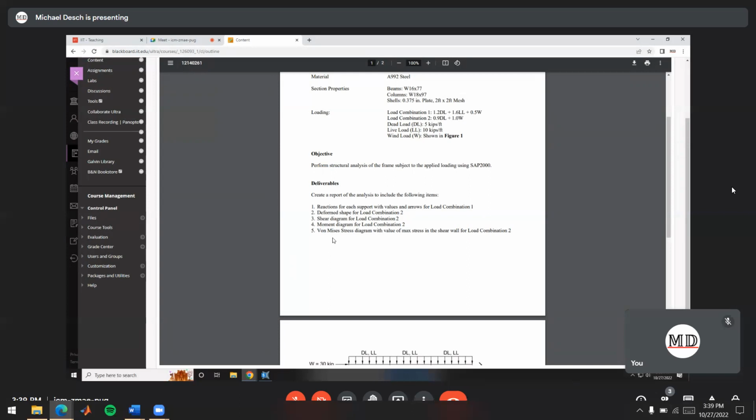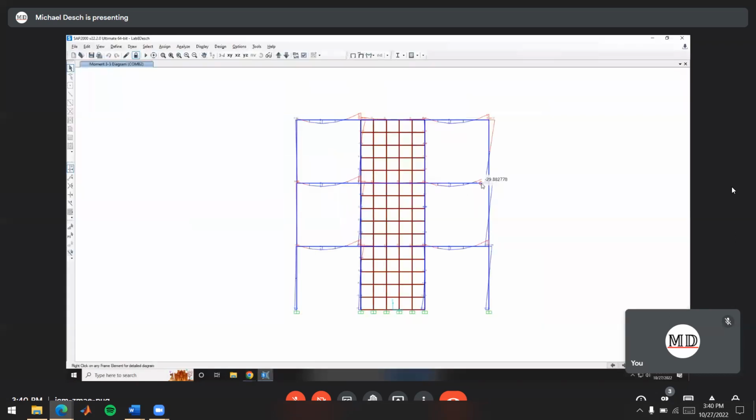We don't really cover this in structural analysis too much because normally we're working with these 1D elements that we need shear and moment for, or those stresses for, and we don't need to get into the stresses in all the plates and stuff like that. You can look it up. It's a square root equation with like 5 or 6 terms in it. But what it does is it takes all the stresses in the different directions and makes one number we can compare against our yield. So it's nice in that way. It's a simplifying measure. So what we want to do is look at that diagram to make sure all that material is still good, basically.